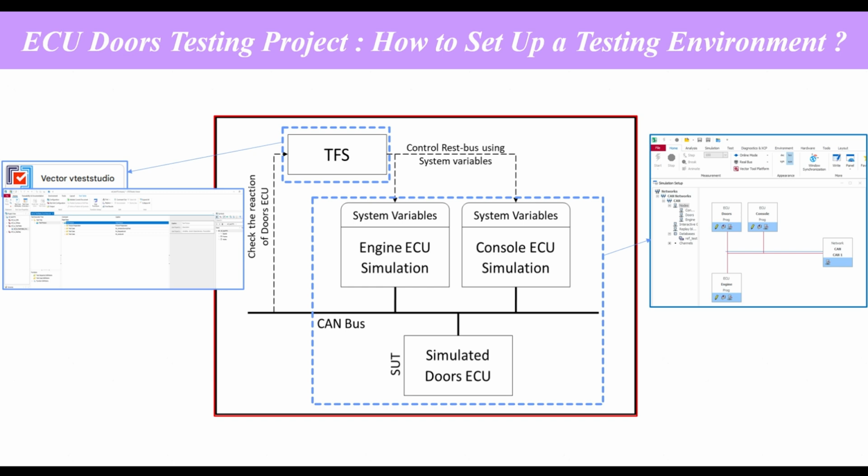Also, you can prepare some software tools, like the tool that you can use to flash your ECU, and also prepare your configuration in CANoe if you use Vector CANoe as a tool. Also prepare your test cases in Vector vTestStudio, for example, if you use it as a tool to define your automatic testing. So this is in general.